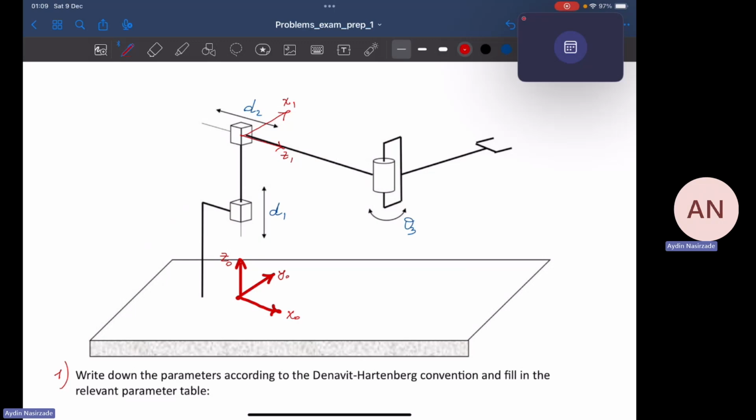Now, let's move on to the next joint, which is a revolute joint, and we know that the Z-axis should be chosen in the direction of the rotation axis, which is either upwards or downwards. I'm going to choose the up direction, so it's going to be something like that. So this is my Z2, and what about X2? Now, intuitively, I can choose X2, this one, right? But no one guarantees. Let me put it this way. No one guarantees that the X2 axis, right?